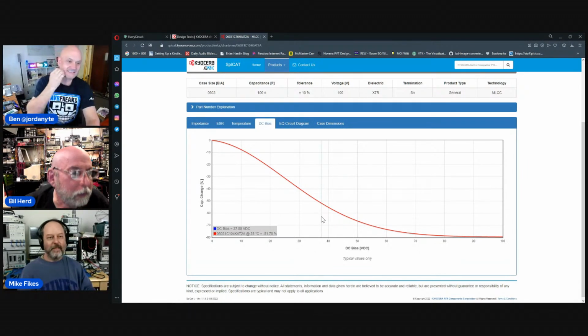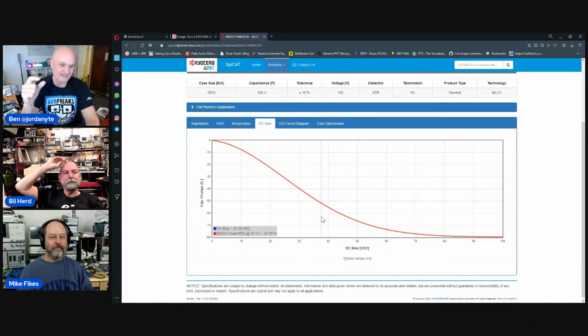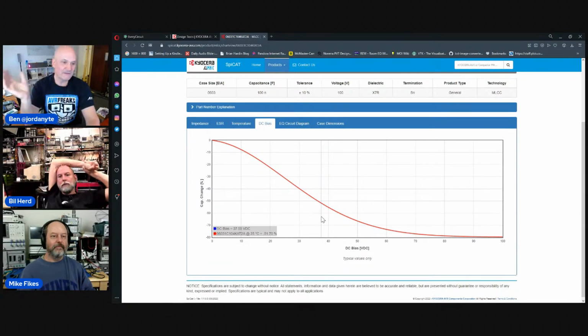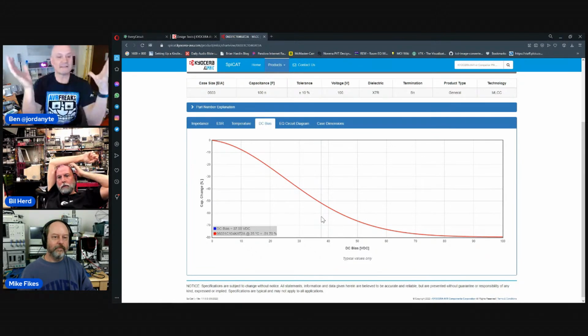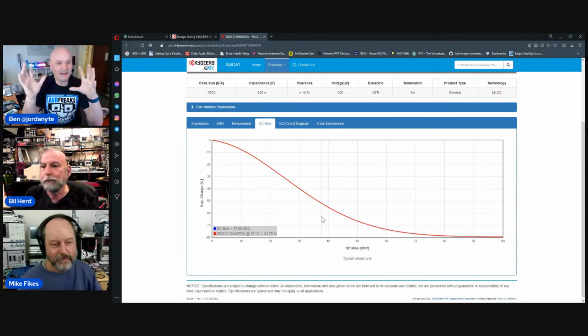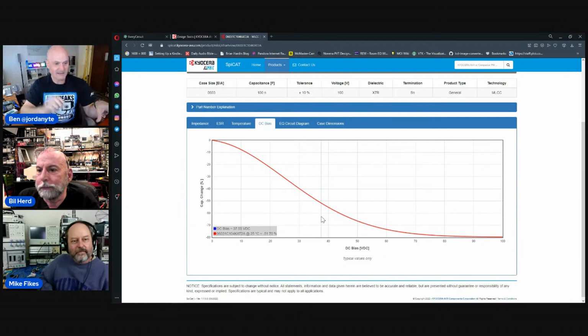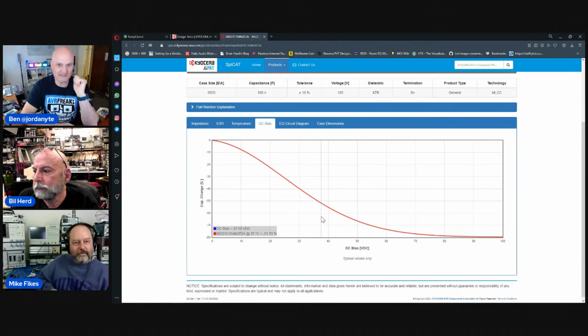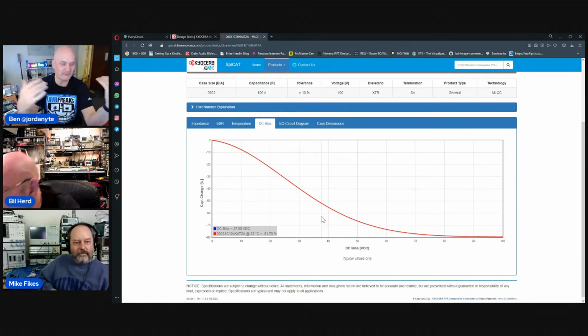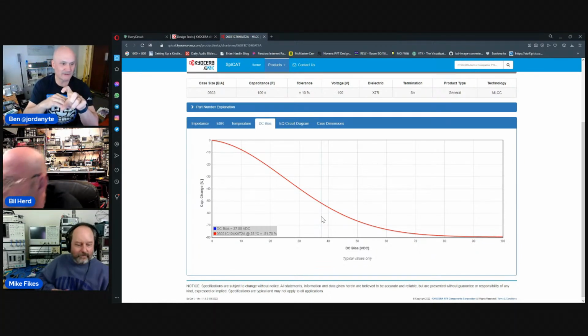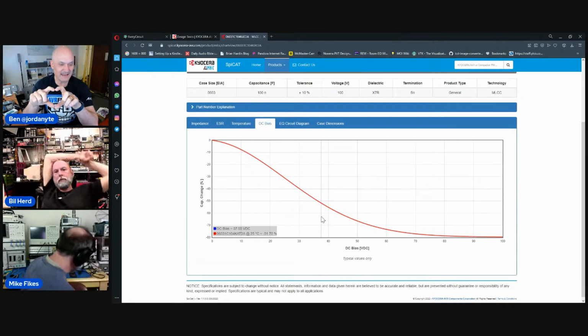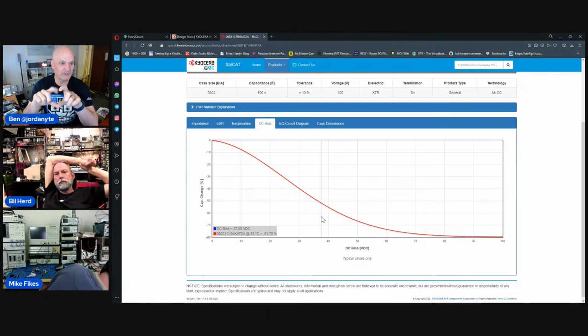And of course, it should not surprise anyone. Let's put it this way. I have a 12-volt power supply and I'm decoupling it. So I buy 16-volt capacitors because 12 is well within the range. No problem. And yes, they'll store energy at 12 volts, but their capacitance is now less because you've charged them up already to 12 volts.